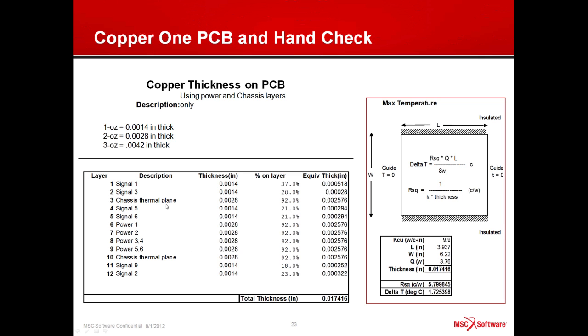When you have power planes or thermal planes, they'll be virtually 100%. In this case, like 92%, about 8% of open space, and it was almost all copper. And they're usually thicker, 2-ounce copper, which in English units is 2.8 mils thick. You take the 0.92 and multiply by that, and you get an equivalent thickness. If you would melt that copper over the whole board so it flowed 100%, it would then go down to 2.5 mils thick instead of 2.8.